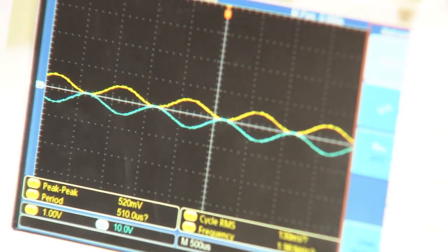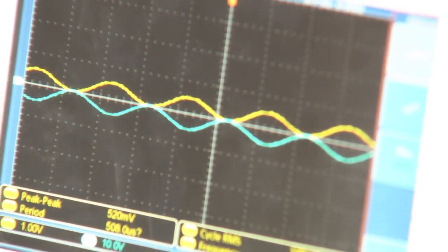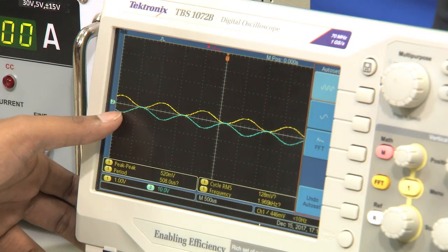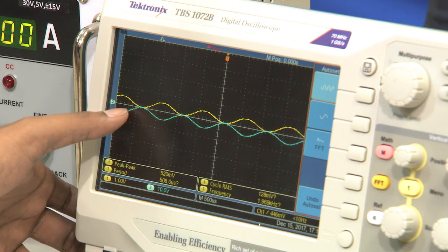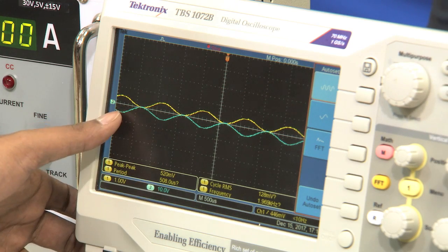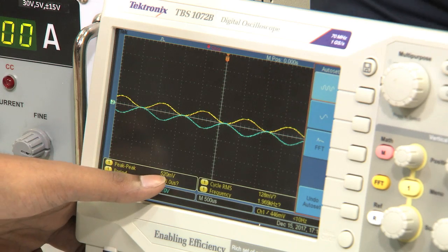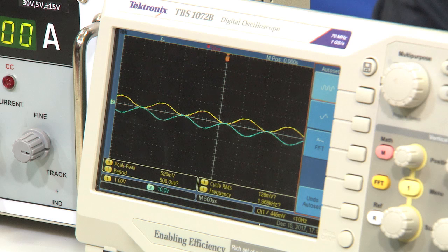So, from here to the oscilloscope. Now, what are we looking at on the oscilloscope? We are looking at some change in the output voltage. What is the new value? You see again there is a phase shift, the output voltage now is from 1 volt to about 5 volts. See, peak to peak is 10, but the voltage that you can see at the output is nothing but 5 volts, all right. Or you can say 520 millivolts.